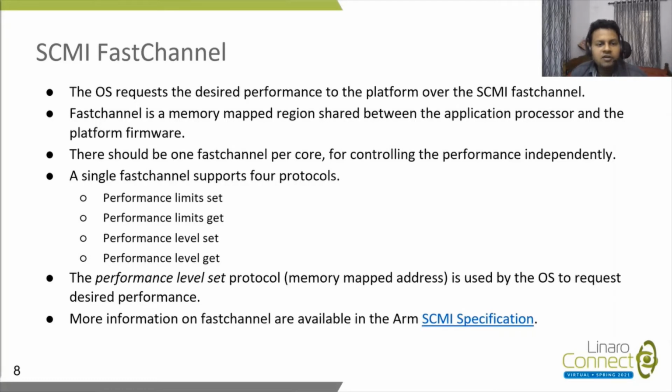And a single fast channel supports four protocols: the performance limit set, performance limit get, performance level set, and performance level get. The performance level set protocol is the protocol used by the OS for requesting the desired performance from the platform firmware.